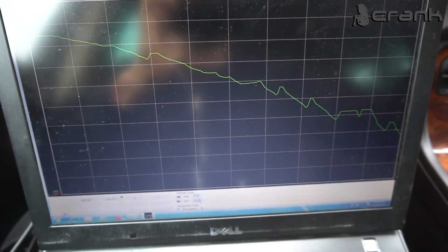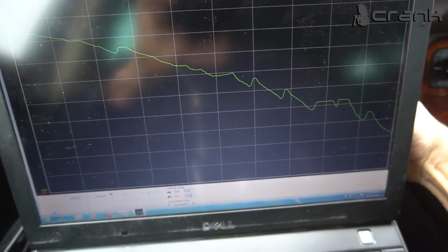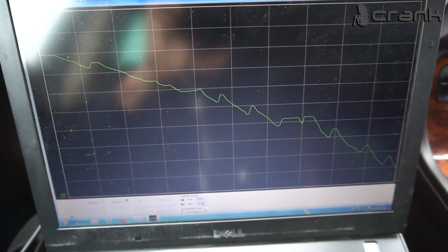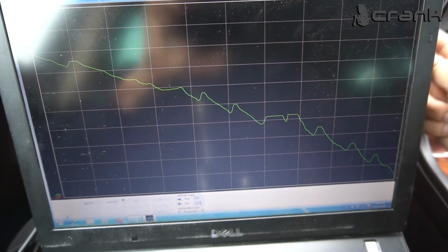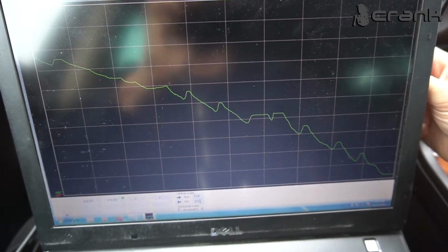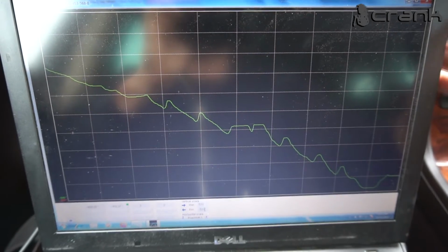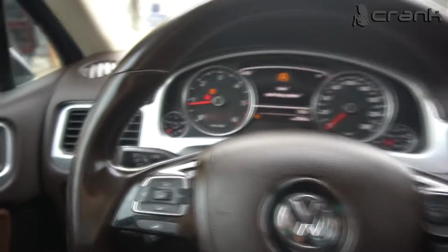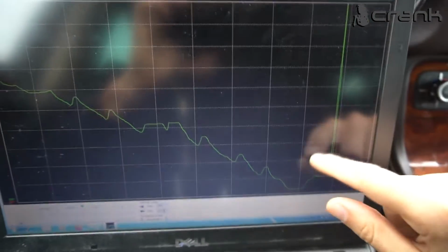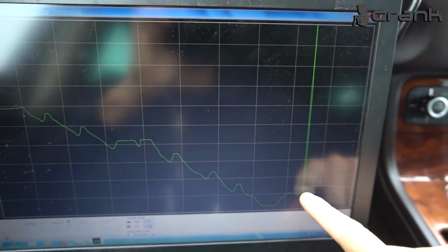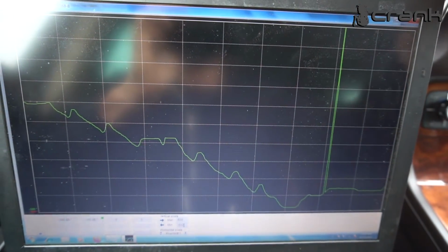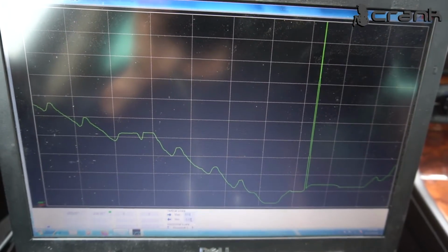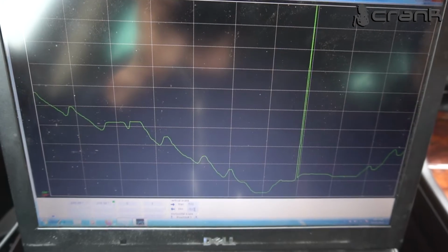We are searching for something really abnormal, which is going to trigger this fault code, which the control unit is searching for if there is an issue. This is the end position, so once again we're going to go in the reverse direction. Oops, as we can see, the fault code triggered right away, and I was talking about this, and after that we go straight back to the normal behavior. This is what the control module is seeing. This is why it's triggering the fault code.